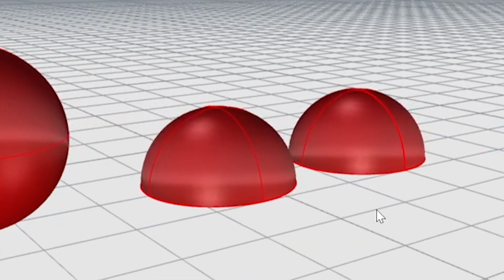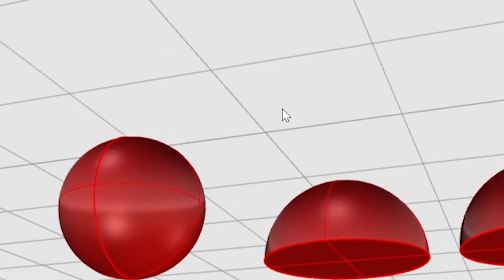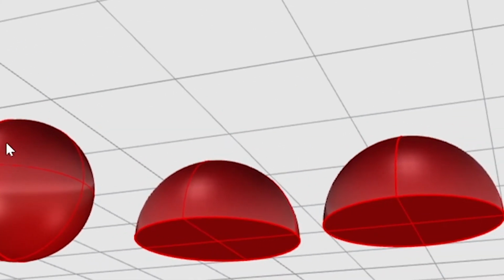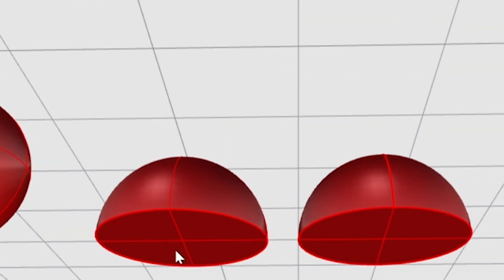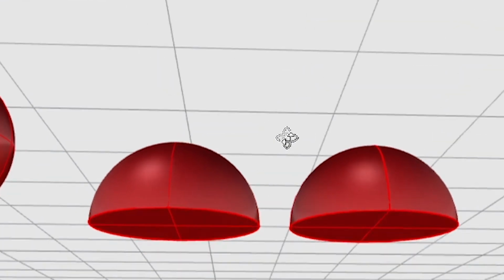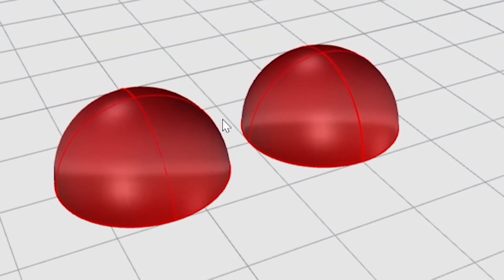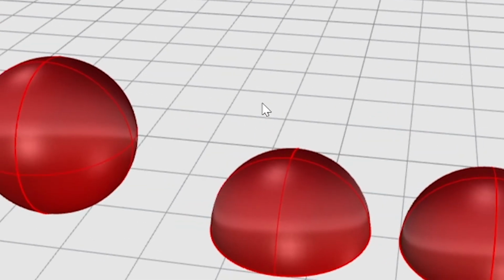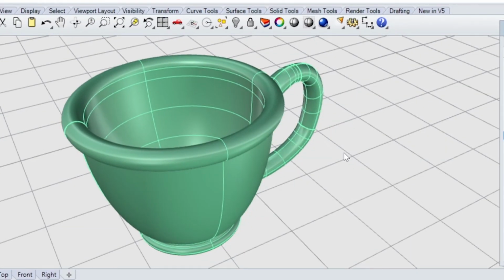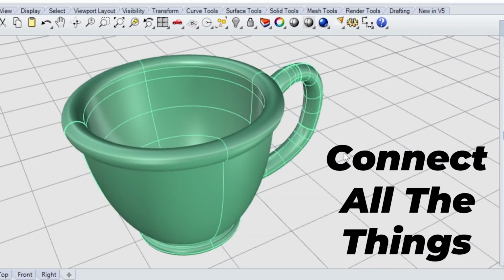In this case, we have a split sphere. So instead of touching the plate at one point like this ball would, what we've done is we've turned that ball into 2 domes that have a broad surface area, lots of contact, high chances of success. And once they're done printing, we can take these 2 pieces and then join them back together to create, in this case, a sphere. All right, let's cover one more lesson with a slightly more complex object in this teacup.